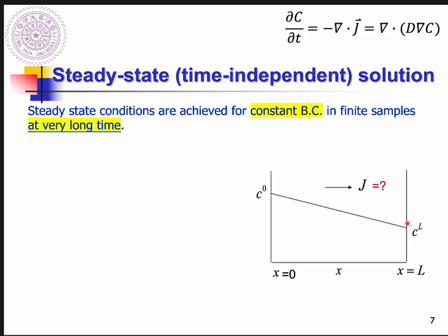And we find this profile, this slope. After different time points, we measure the concentration profile again, and we find this concentration profile does not change with time, always looking like this. So the question is: what is the flux, and can you prove that these conditions are steady state? In order to know that, we need to make sure the concentration profile does not change with time, so partial C with respect to t equals zero.